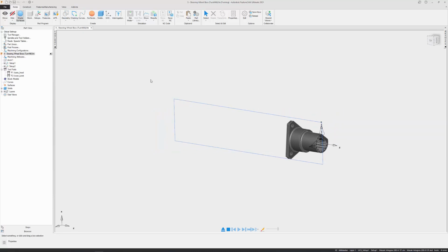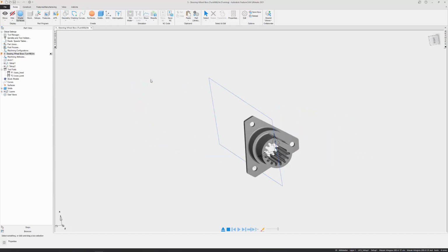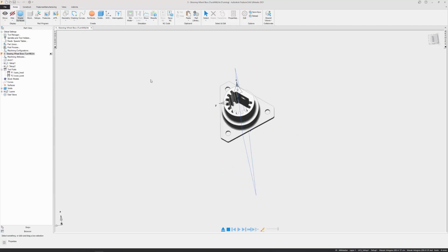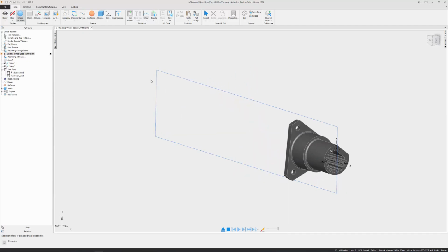Now, very similar to the wheel hub plate that we created, we're going to do this using two different operations. The first of which, we're going to use a turn mill style setup using our Mazak Integrex to do both some lathe work and some live tooling work to get a near net shape here. And then finally, the second operation is going to be on a Wire-EDM machine in which we cut out this middle area that is particularly well suited for the strengths of our Wire-EDM machine.